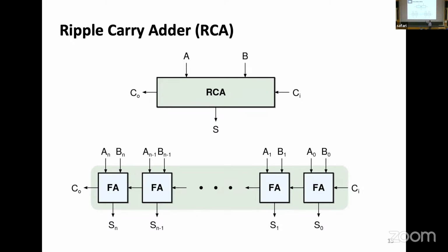And now once you zoom in into this, we can go back and take our beloved full adder, the one that was so boring. And you realize I can take a full adder. This is the carry in that I was talking about. I take A0, B0, so the 0th bit of the vector A and the 0th bit of the vector B, and I calculate the sum. Now, if this sum has a carry, I pass it to the next full adder, which is a carry in, and B1, A1, and I create the sum, and I pass it, and pass it, and pass it. So if I have n bits, 512 bits, right? So A511, B511, sum 511, and finally, if this guy still has a carry out, he will spit it out. And that's it.